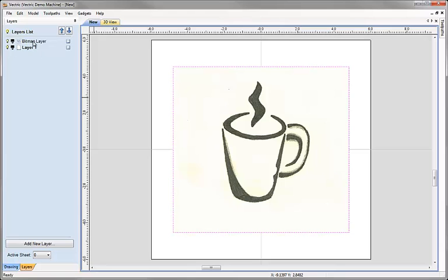Now it is possible for me to rename that, reorder it, even to draw vectors on that layer. It's not a special layer, it's just something that the software creates to make it a little bit easier to keep things organized as you import them. And generally speaking, we'd advise that you keep all the images on the bitmap layer and don't create vectors on that layer. So generally speaking, you're rarely going to select that to be your active layer.